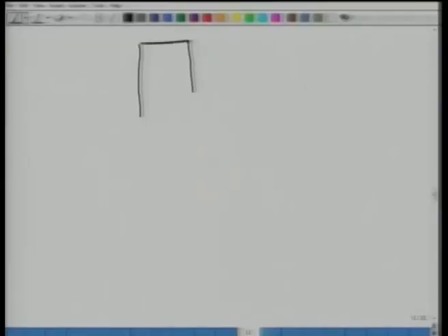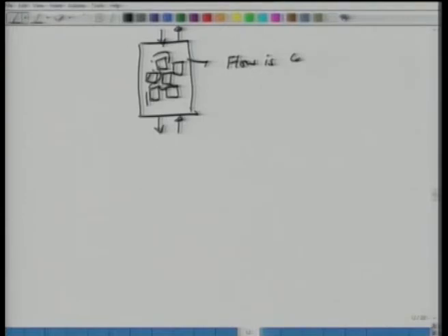So if you have the packing like this, where we have certain packings stacked, it could be spherical, could be cylindrical, etc. It's quite a complex velocity profile. The liquid goes like this and gas flows through this, across this or between the pores, micro pores of cylinders, and this gap here, the flow is quite complex, in which case again the necessity of mass transfer